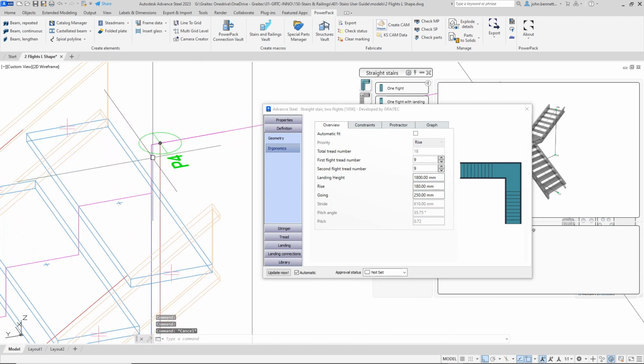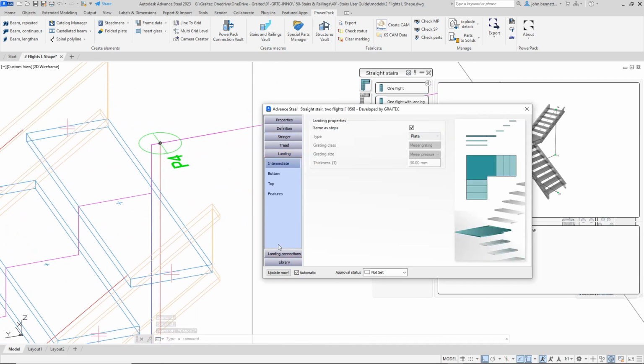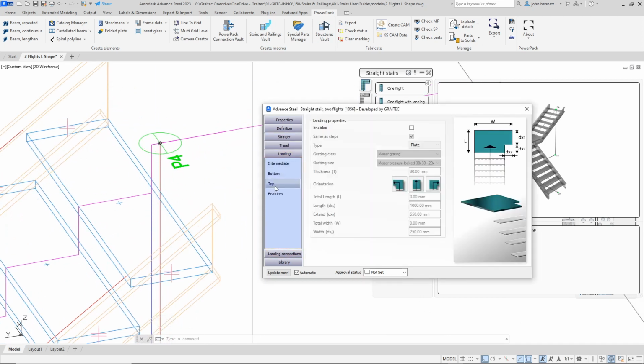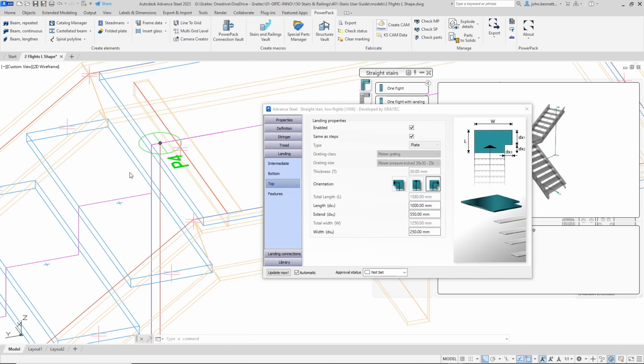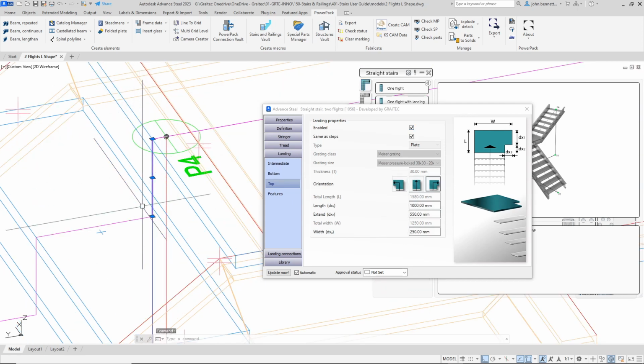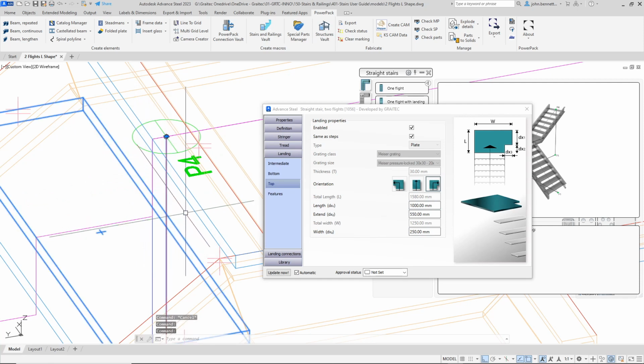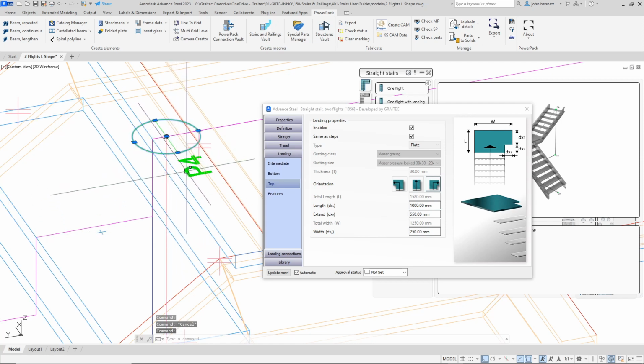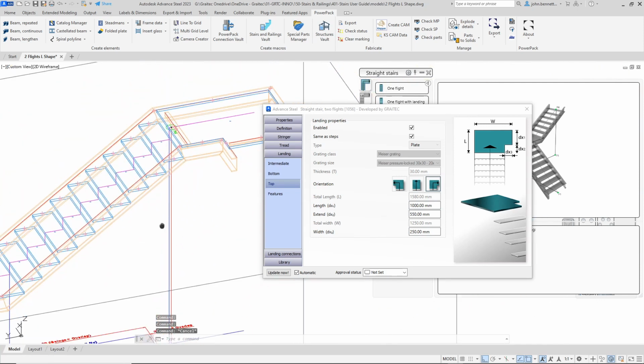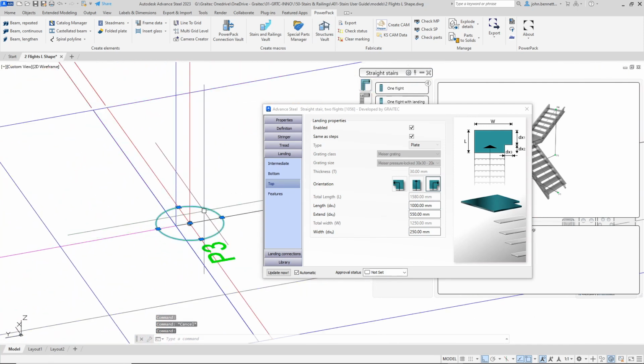And importantly here, if we were to come in and turn the landing element on, so if we come to the top landing element here and enable that, we will see the top toe of the stair flight, which is actually the landing toe as well, and that will appear, and that is formed in the correct place, with obviously the overlap value here for this tread matching the red line that we'd indicated before, and we'd use to create our 0.4 for the height and the overlap position based upon 0.3 down here.